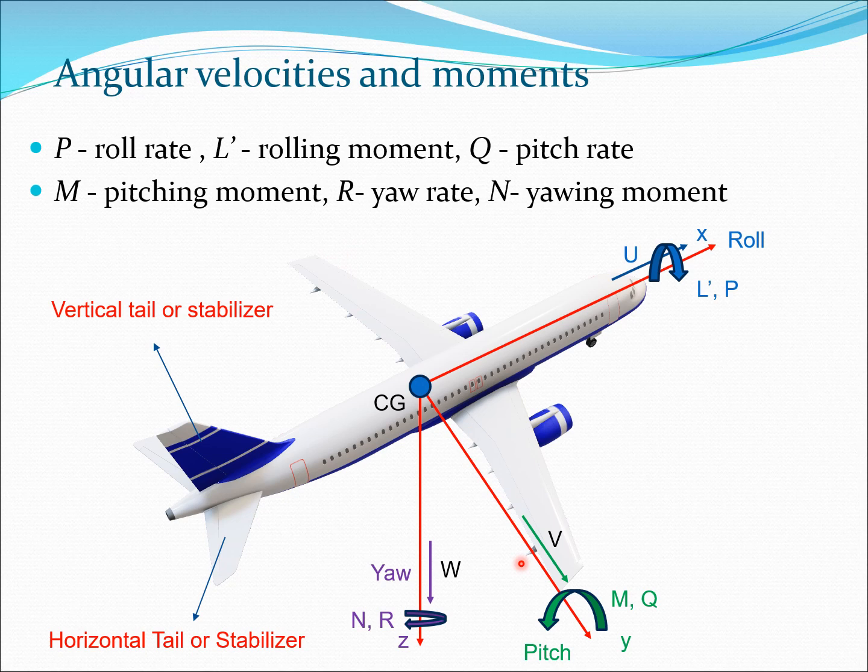Also, if you look at any aircraft, we of course have the wing. This is the source of lift which is required for the aircraft to fly in air. But we also will typically see a horizontal tail and a vertical tail. So these surfaces are actually required for stability. We are going to discuss that in more detail later in this part of the course. Sometimes these are also known as the vertical stabilizer and the horizontal stabilizer. So essentially you will see some analogy with fish and bird type of systems.